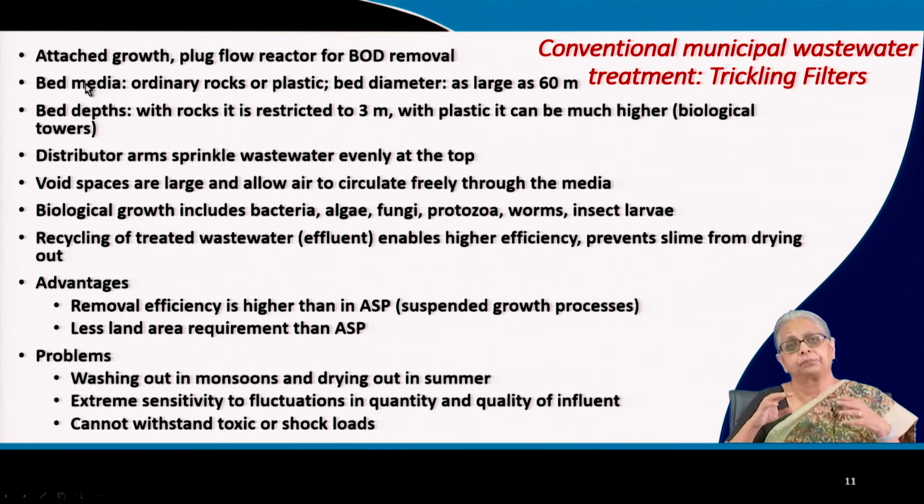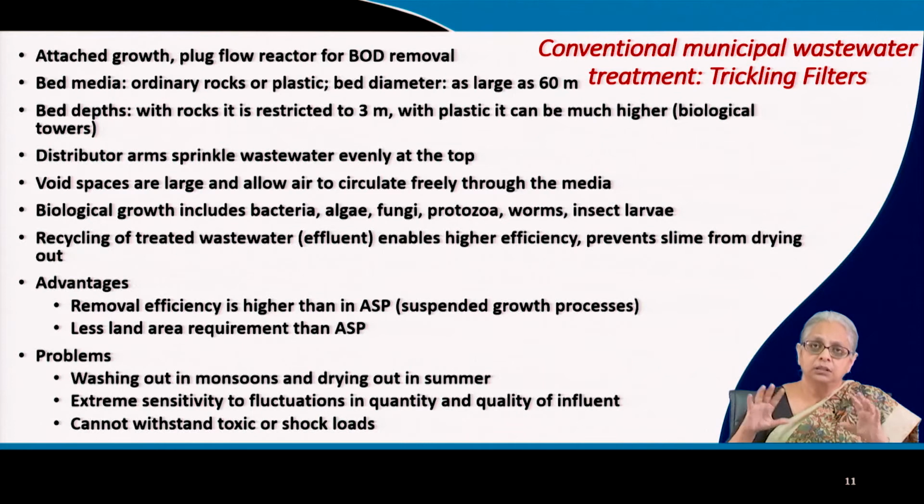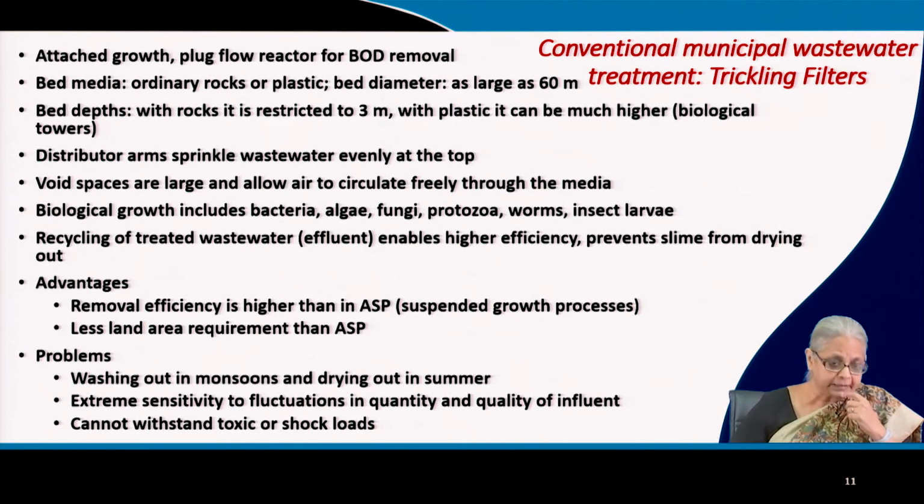When I said attached growth, it means you have to provide a media on which the bacteria will grow. So this media can be ordinary rocks, stones, and or plastic. And these are some of the most common materials that are used. The size of these reactors can be huge in both cases, ASP as well as trickling filters.